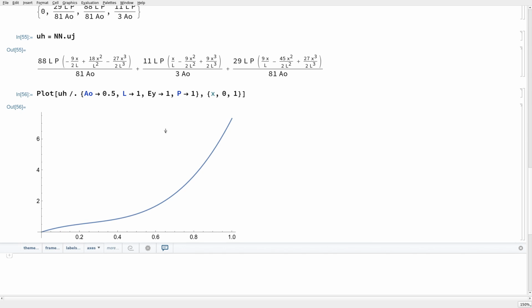In which situation would we want to pick the test functions differently from the shape functions? Until you have a reason otherwise, you always pick them the same. This is the standard Galerkin approximation. You would always do it. And this is like 90% of all finite element methods, finite element codes.